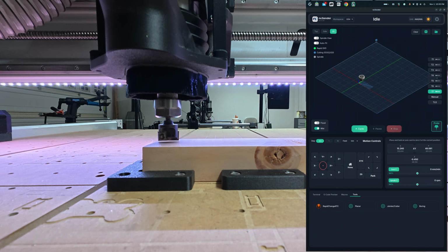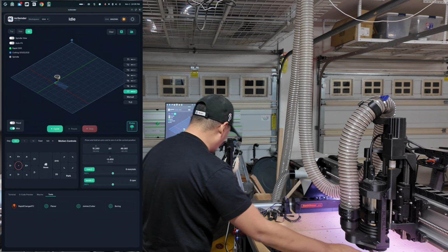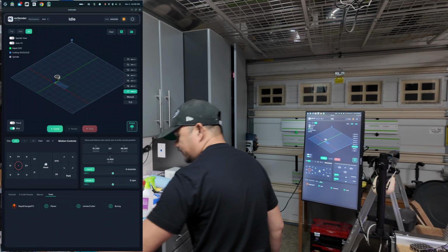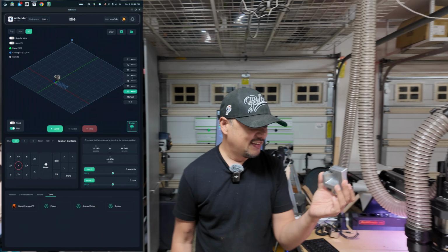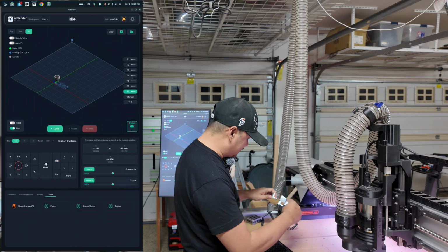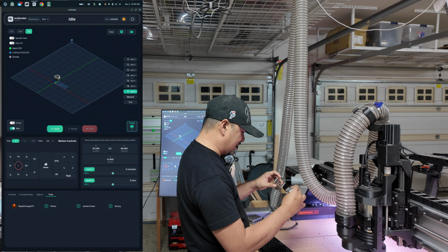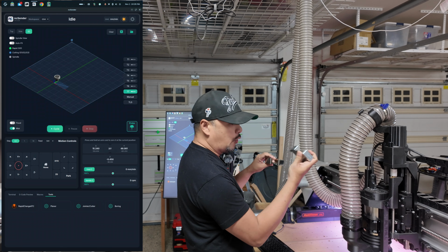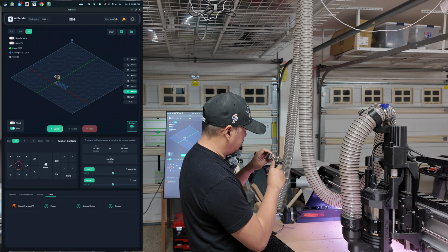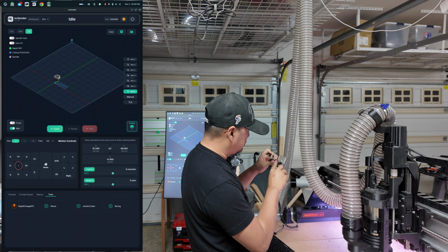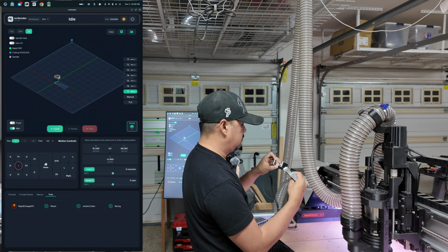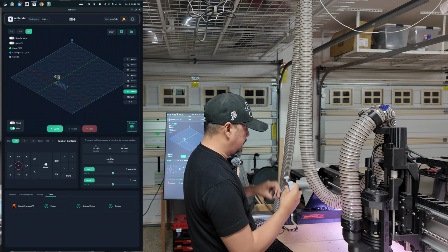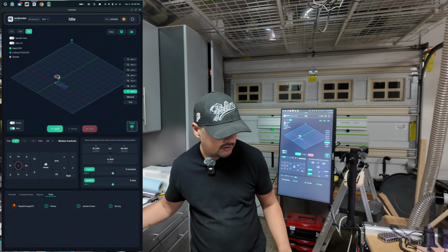So I need to adjust the programming of this because this is a static number. Because I used my clone one, I guess they have a different thickness. Oh yeah, they have a different thickness. That's the reason. I think I programmed it using my clone one versus the original Auto Zero touch plate, which I think might be more than 5 millimeter. Yeah, okay. But it's not the problem.